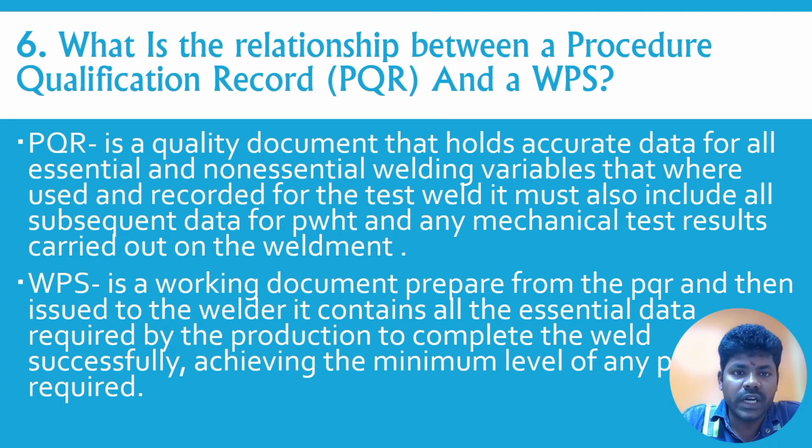Okay, what is the relationship between a procedure qualification record and WPS? WPS means welding procedure specification. PQR, what is the relationship between PQR and WPS? This is the question. And the answer is, PQR is a quality document. It holds accurate data for non-essential and essential variables, and it records all the test results, PWHT and mechanical results carried out on the weldment. And WPS is derived from the PQR. The PQR is the mother document. WPS is a separate document.